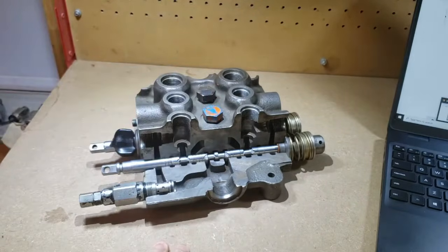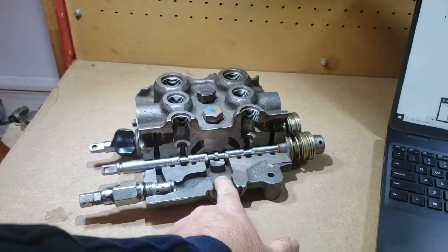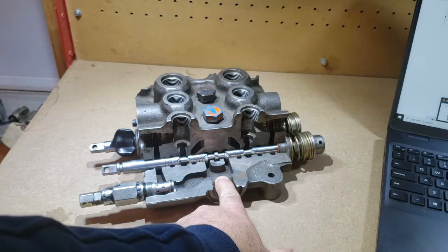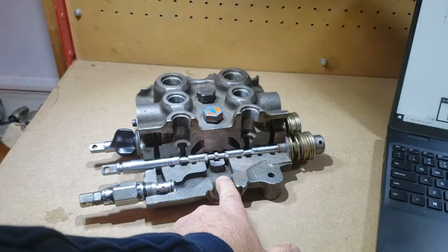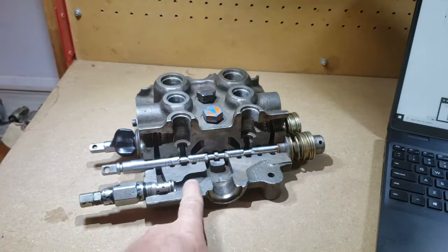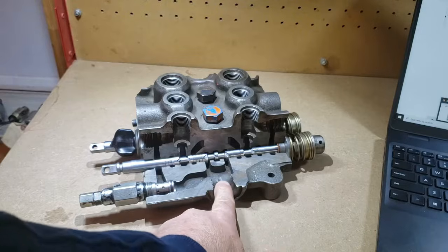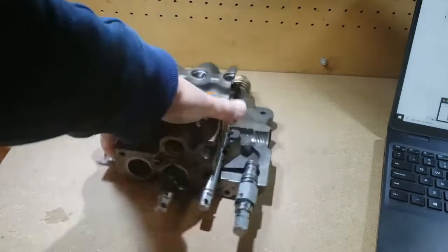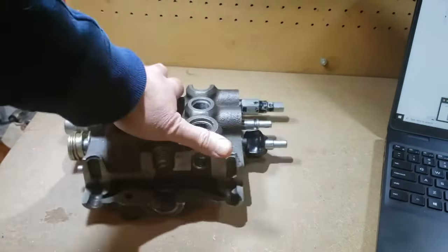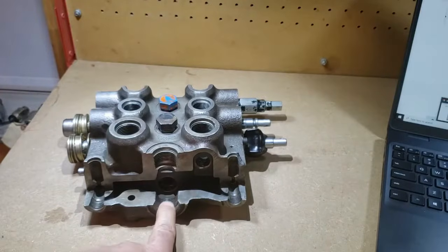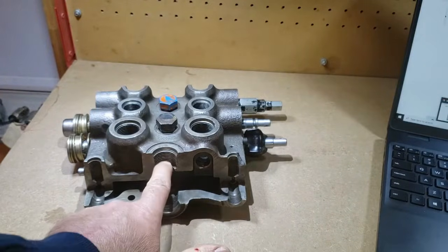It's basically got 10 oil connections to it. It's got the supply coming in here where the oil from the pump feeds the valve. And I can tell that because here's my main relief just perpendicular to that inlet. And then around the other end of the valve, it's got the return connection here. So oil comes out of the valve this way or this way.